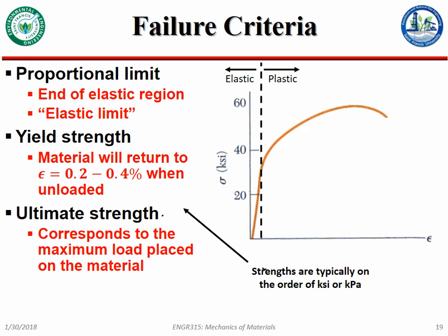So that'd be an instance of why we'd want to care about yield strength before ultimate strength. So we care about down here instead of up here because of the physical implications for the material itself. So are we all on board with that?